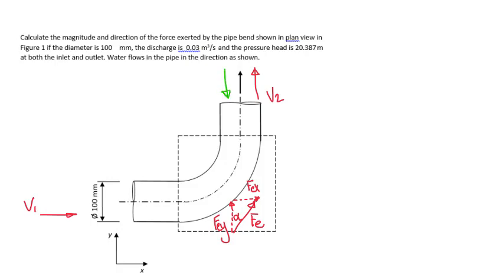The pressure will be in the opposite direction of flow because the pipe continues. This symbol here shows you that the pipe is continuing. Okay, so let's call this pressure at point 2, and here at point 1, the inlet rather, pressure 1, and that's also in the same direction of flow.